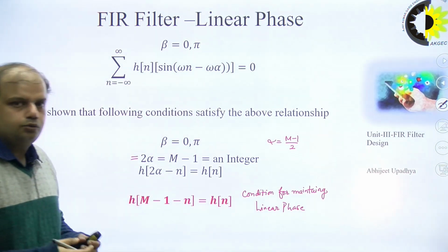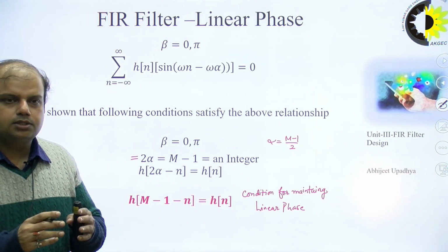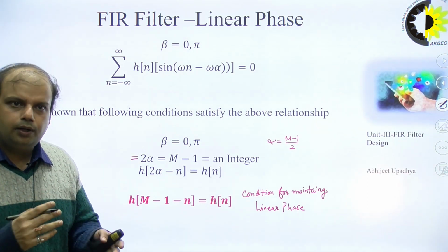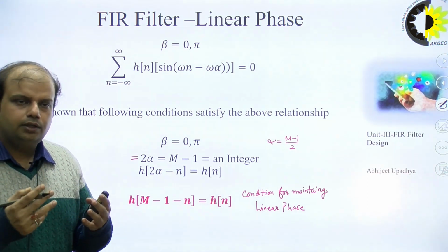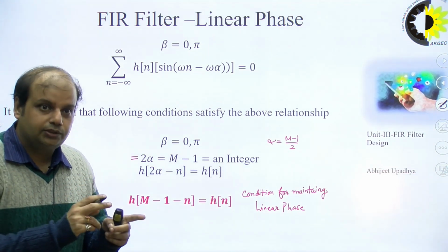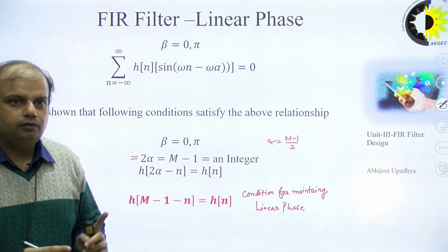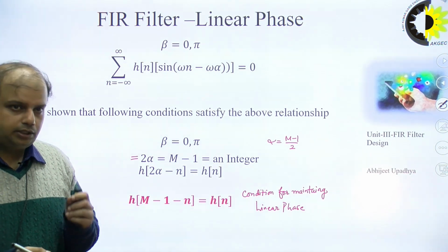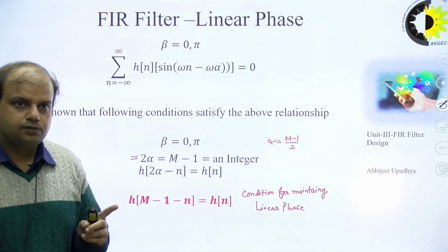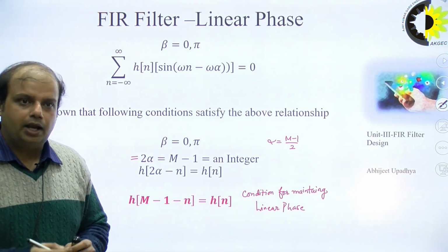So the proof of linear phase comes from this: we calculate the phase of the system, the same frequency response, using either the DTFT or Euler's theorem. We equate them and solve the equation to get a solution. The solution provides the criteria on the impulse response, that they are equidistant from both the ends, which we have seen in one numerical also. So either using a windowing function or any other means, if the linear phase is there, the FIR filters' impulse responses, which are actually equal to the filter coefficients, are equidistant from both the ends, and that completes the proof and the lecture. Thank you.